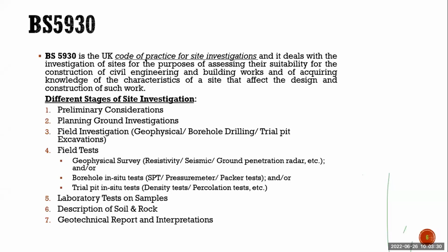If it is not deep, they will perform trial pit excavations. In that way also we can identify if there is a cavity. Or if they are sure there will be no aquifer in that region, they directly go for borehole and trial pit excavation. Okay, then field tests.